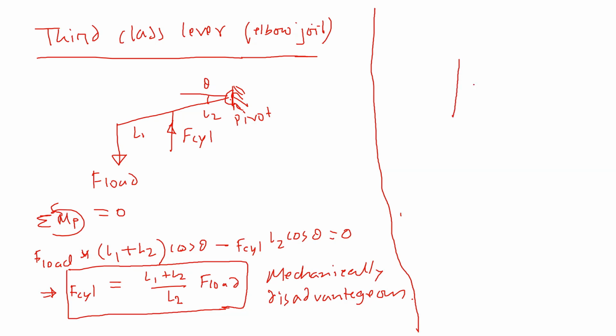If we have a cylinder like this, imagine it is pivoted right here. So if the cylinder is pushing or pulling a load like this, let's think about the first class lever example. This is the load. This is the pivot point. So when this cylinder is, for example, pulling down, this has to rotate, because this is a solid cylinder, it cannot just go down without rotating.